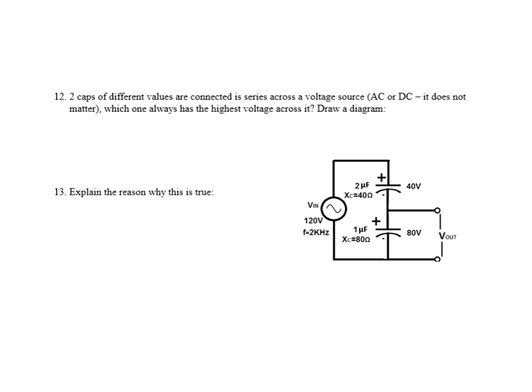The reason behind that is that it deals with charge in the series circuit, and in the series circuit the charge is the same. But we know that the charge divided by the size of the plate, or the farad value of the capacitor, gives you the voltage. And so if you have the same charge on both capacitors, and the farad value is bigger on the other, the one with the bigger value will have the farad value in the denominator, and that will work out to be a lower voltage. So when you see capacitors in series, the smallest capacitor will always have the larger voltage.